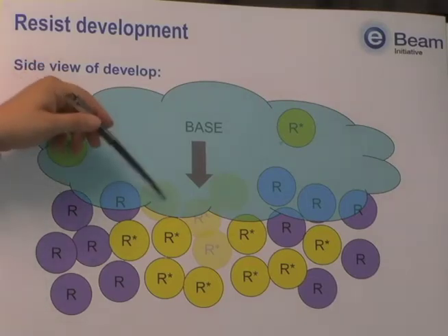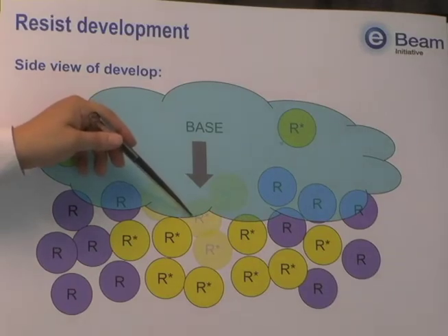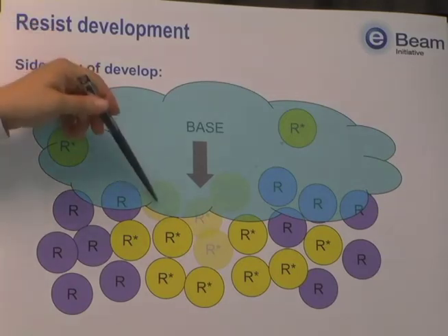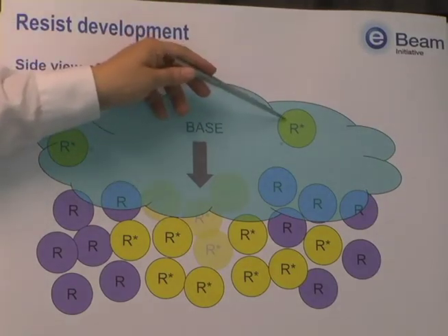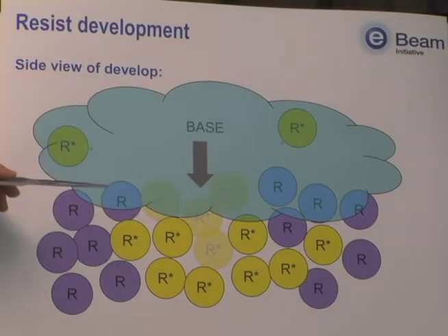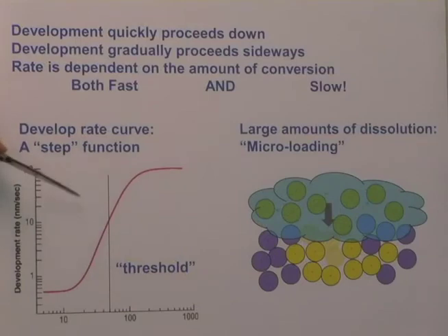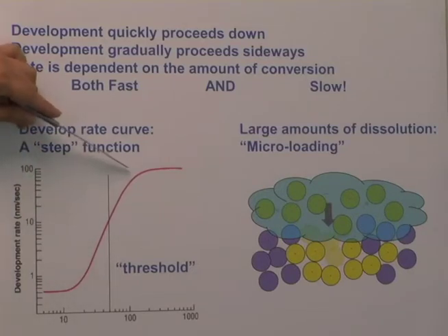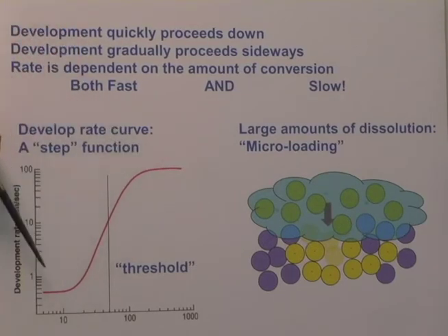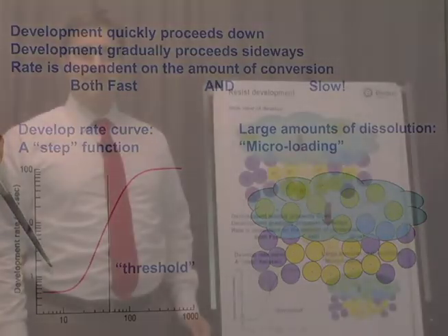However, those portions of the resist that have been switched have an increasing affinity for dissolution, such that the rate at which the resist is dissolved into the developer is dependent upon the overall percentage of the resist that has been reacted. However, this dependence on the overall percentage of resist reaction is not linear. In fact, it's almost step function-like, where there can be thought of as a threshold reaction percentage over which the resist is completely soluble and under which the resist is completely insoluble.